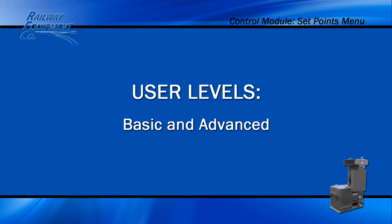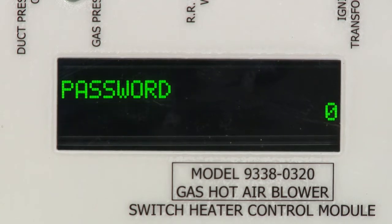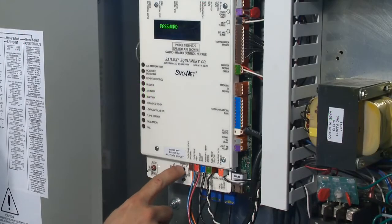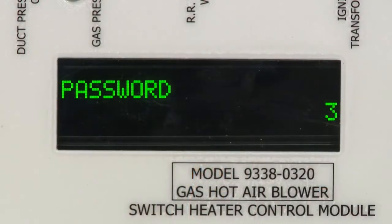The user-level options are Basic and Advanced. Basic allows access to basic menus, but a password is needed to access advanced menus. To enter a password, use the increase or decrease value buttons. Password 5 allows advanced menu items to be displayed and to be changed.